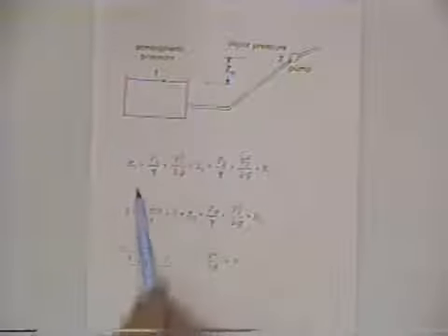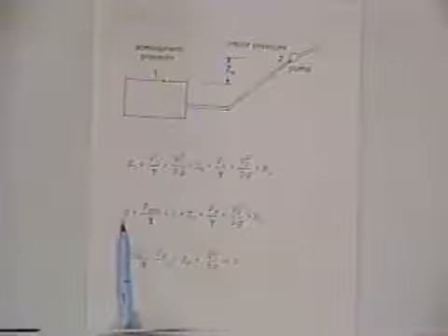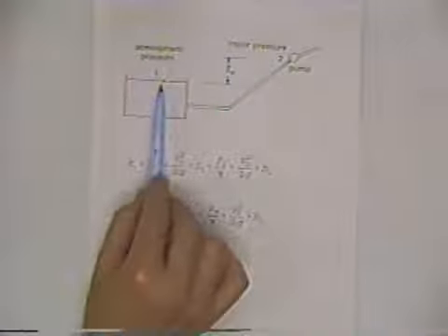We've got the pump some distance above the water surface, the Z sub P, and it very well could be in another problem that you're actually solving for the Z sub P, given that you know the Q. And so if you look at the energy equation, it's going to look like this, and you're going to be plugging in the atmospheric pressure. You're going to be on purpose setting points 1 and 2 so that you can plug in zeros for the elevation head and the velocity head there, and you're going to have these terms, and then it's going to always come out to this expression. And of course the numbers will vary depending on the problem.